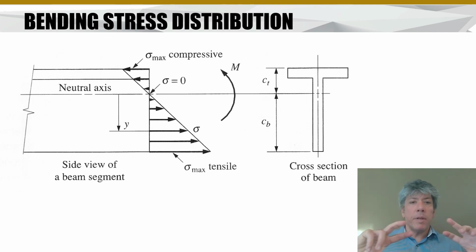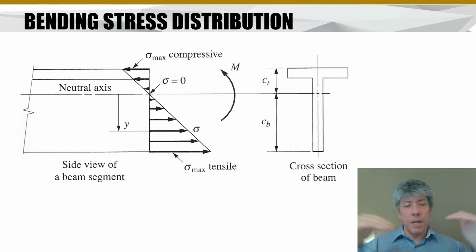And so if you took this beam and you turned it upside down, where the straight section of the T is now at the top, well, now that section is going to be in compression. And so you'll still have a high load, but you can reinforce, you can add material where it's needed in the flange where the material is not good at tension, because if this is upside down, obviously the flange portion is going to be in tension. So that's one strategy for overcoming the imbalance in strength that a material has in tension versus compression. But of course you have to be very careful about buckling in that case.